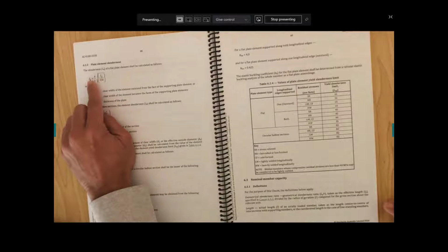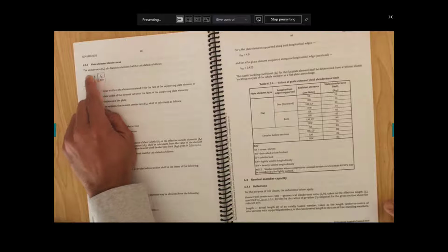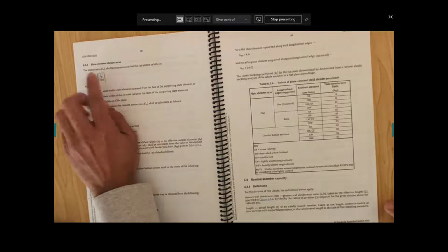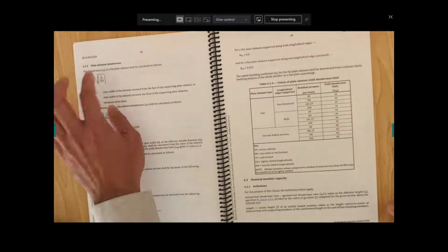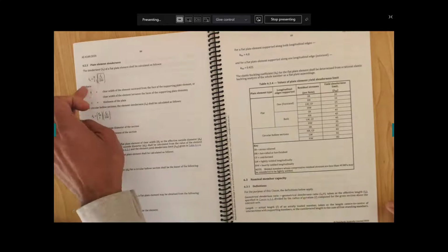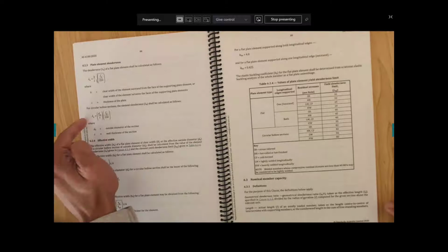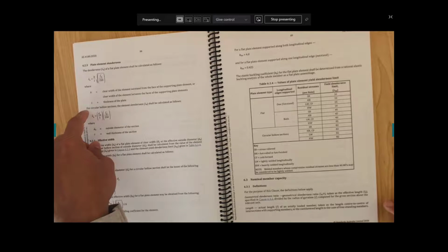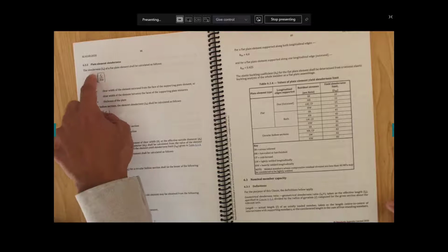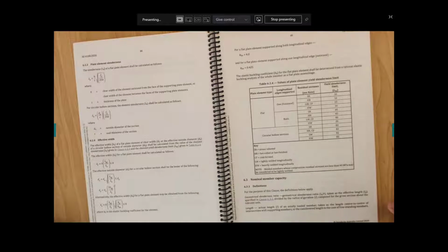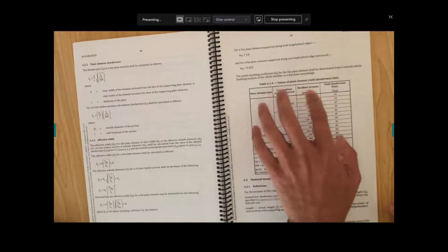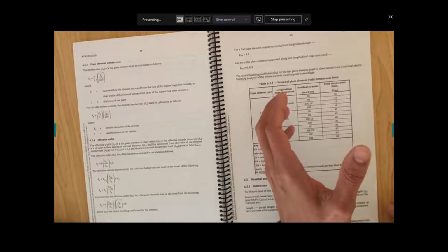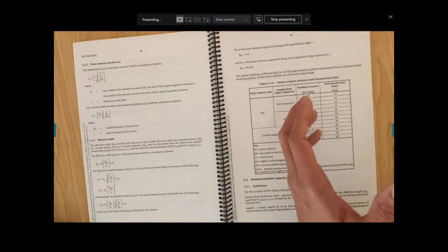So lambda e equals b on t square root fy on 250, which is the plate element slenderness represented by lambda, like in the beam. So we get these equations, we're going to calculate b, we calculate t, and for circular hollow sections we no need to worry, we just want to worry about this flat plate. So we calculate lambda e, and we compare against our yield slenderness limit. If lambda e is less than lambda ey, it is fully effective.